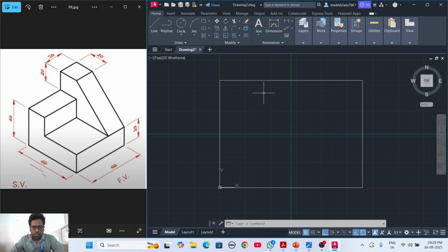So now my front axis will be in this quadrant for the front axis. This will be the side view. In this quadrant I'm placing the side view, and from the top view I am using this quadrant, as per our standard procedure. And for the first, second, third, and fourth quadrant, we need the 45-degree line.